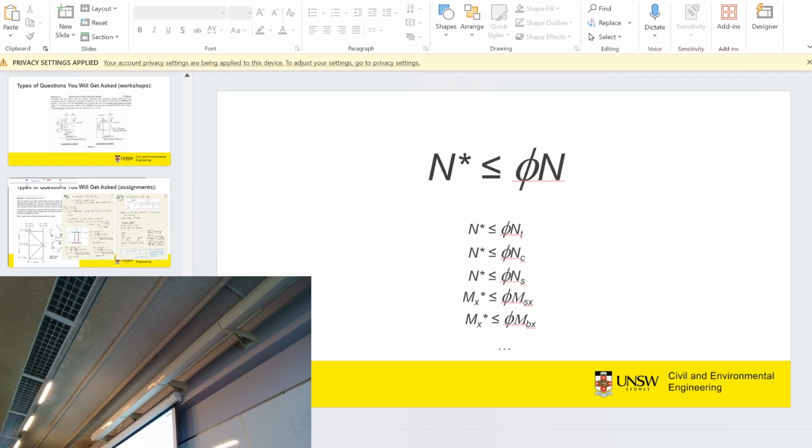You'll scale this side up. And this side is how strong the material is, so it's the capacity. For example, if this is 8 kilonewtons and the material can only take 7 kilonewtons, then it'll fail. But if this is 8 kilonewtons and that is 10, then we can pass it and say, oh, it works. That's the basic thing here.